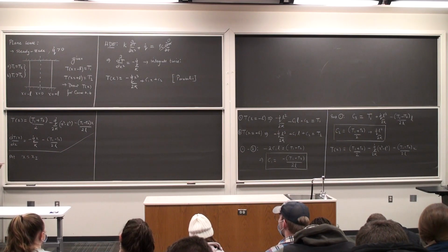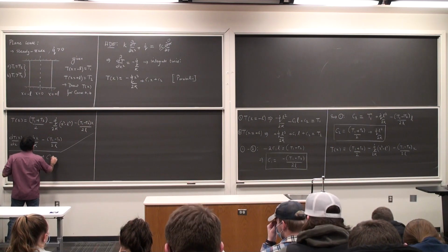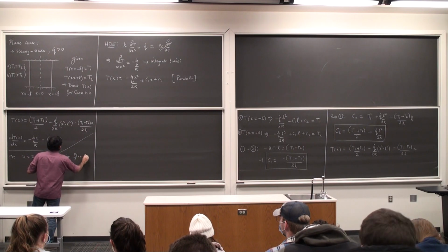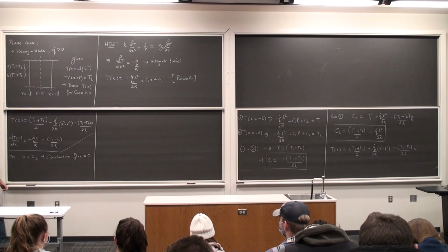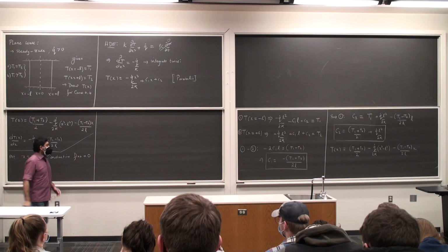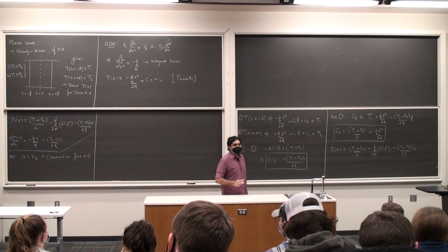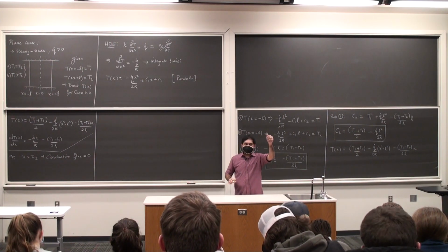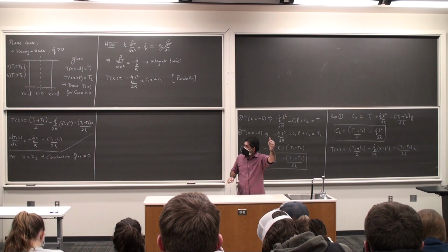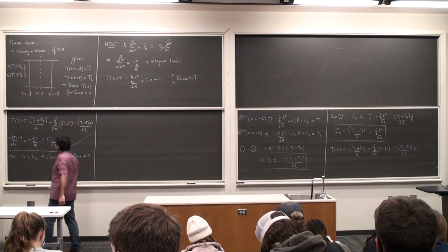I'm going to say that this is a location where the conductive flux is 0. I stand for insulation, right? If the conductive flux is 0 and I need to find that location, how do I find it? Yes? Set that equation equal to 0? Which equation? The derivative? The derivative, right. So this implies that dT by dx is 0 at x is equal to xi.